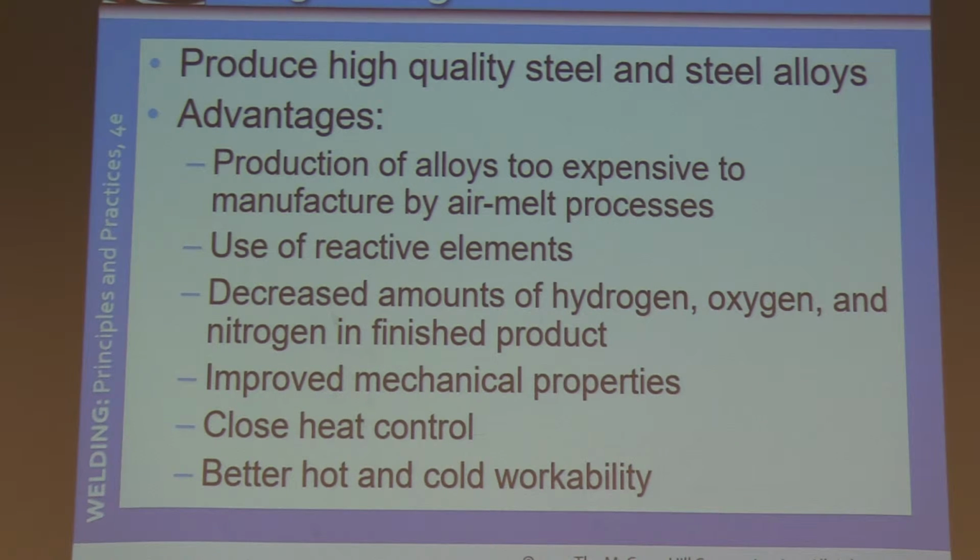Talk about this. The top diagram talks about vacuum processing of steel. Steels for special applications are often processed in a vacuum to give them properties not otherwise obtainable. The primary purpose of vacuum processing is to remove such gases as oxygen, nitrogen, and hydrogen from molten metal to make high purity steel. Many grades of steel are degassed by processing similar to those shown in this page.